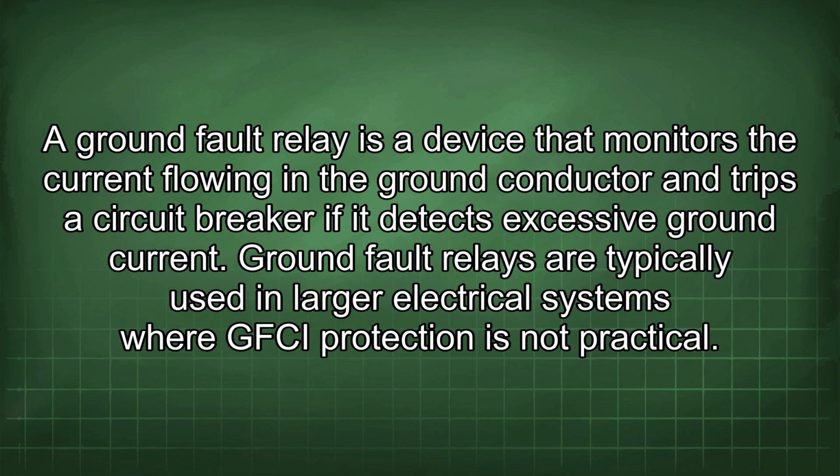A ground fault relay is a device that monitors the current flowing in a ground conductor and trips a circuit breaker if it detects excessive ground current. Ground fault relays are typically used in larger electrical systems where GFCI protection is not practical.